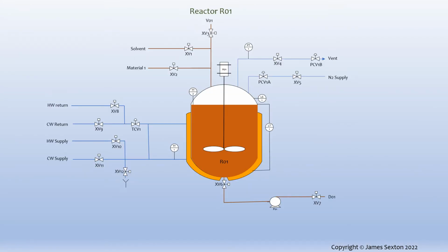Let's examine the reactor to further emphasize this. Since the vessel is the only place that any processing can take place, there are no further candidates to be equipment modules in this unit. It will be possible to mix the batch using the agitator, but that processing is done in the vessel. So that processing is centered on the unit, not on a separate piece of processing equipment. Likewise, it will be possible to heat the batch because of the jacket heating system, but it is again the batch in the vessel that is heated.